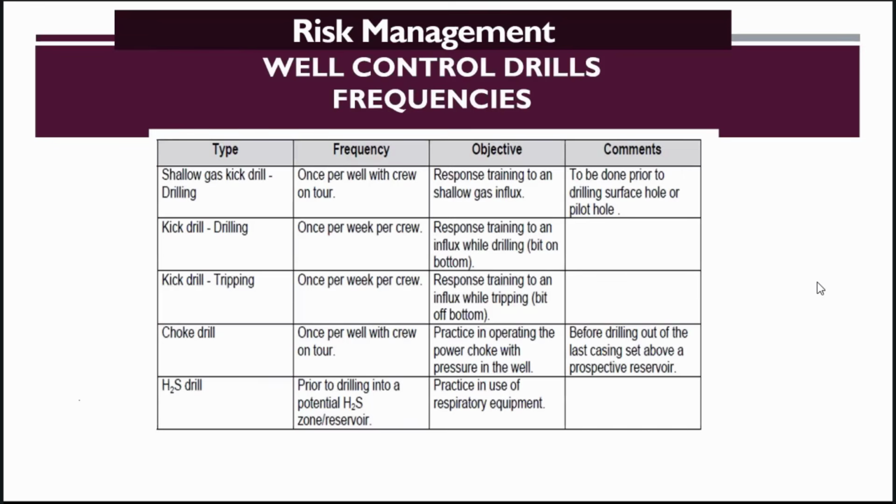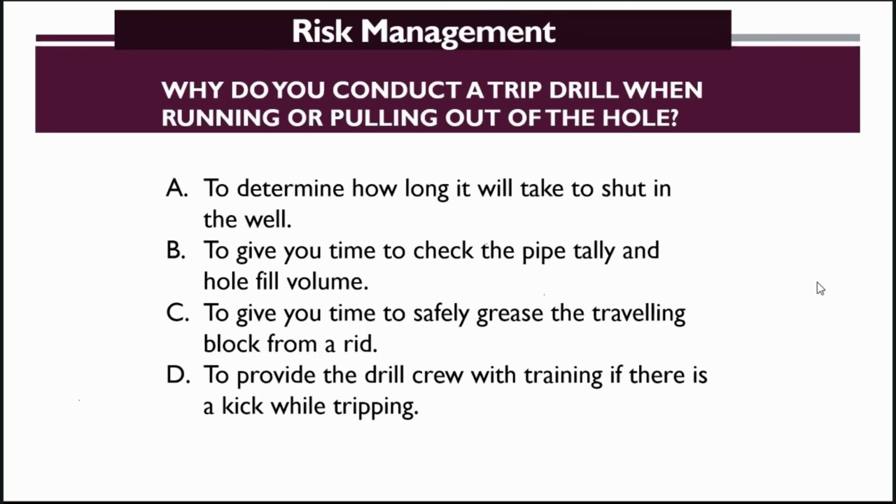Why do you conduct a trip drill when running in or pulling out of hole? When they are running in hole or pulling out of hole, we do the trip drill because we want to provide the drilling crew with training: if there is a kick while tripping, how should they react and what procedure should they follow.